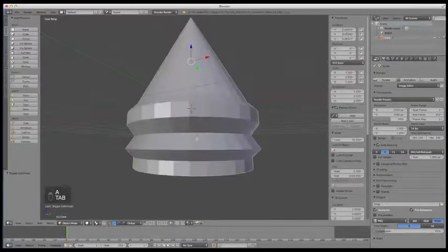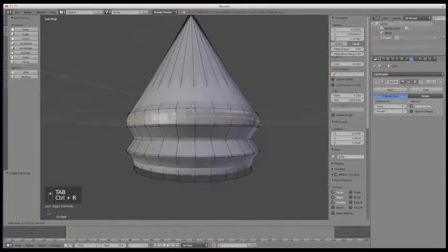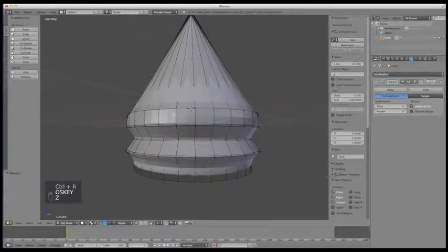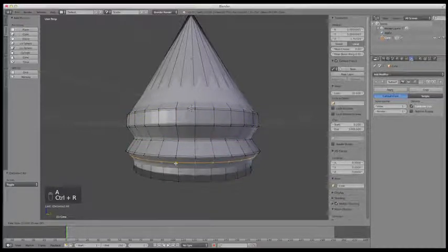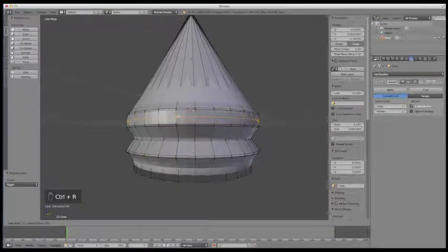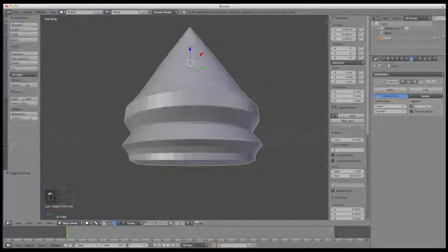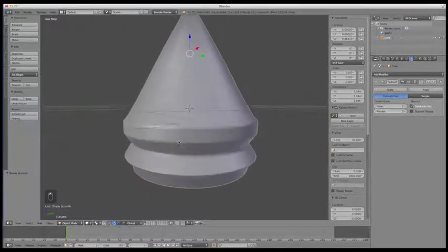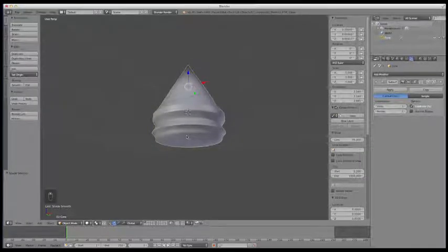So again, really useful. And as you can see, if I go back now and I add a modifier like subdivision, now I've really added some nice edges in right here, 0.8. And I can just keep going in and adding those bordering edges that are really closely bunched up together. And it's going to allow me to really crease these edges out. So as you can see, if I smooth that with that smooth button, now I've got some really nice edges for that tower rooftop. So pretty handy. And again, that's pretty much how I model everything.